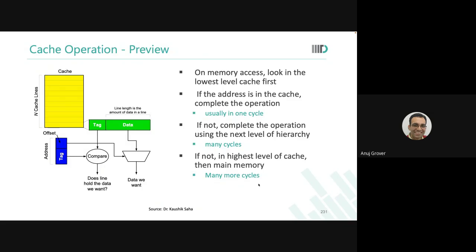That is where you call it a CAM, content addressable memory. Because you have 32 bits which you want to match and see in which particular row I have the full match. Wherever there is a match, that particular location's contents I will throw out to my processor.